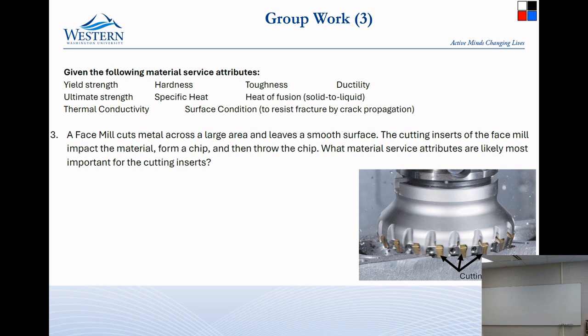So they do the same thing here that they did on that die backer. There's an insert, and then right behind the insert there will often be another little thing that looks like an insert. The insert itself is a very hard material so that it can deform the material, and then they will back it up with something that has better ability to absorb that energy, so it has a better toughness.